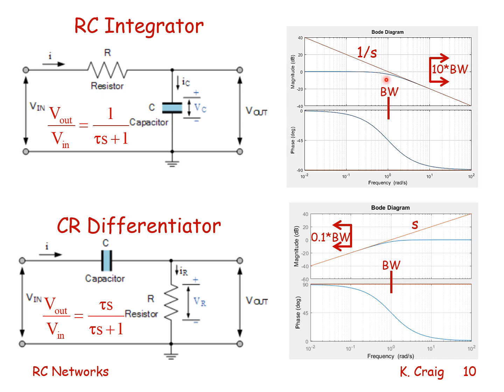At that point, the amplitude is dropped minus 3 dB from the low frequency or DC value, and then it rolls off in a straight line at a slope of minus 20 dB per decade, where a decade is a 10-to-1 frequency change. For example, from 10 to the first to 10 to the second is a decade. From 10 to the 0 to 10 to the first is a decade.